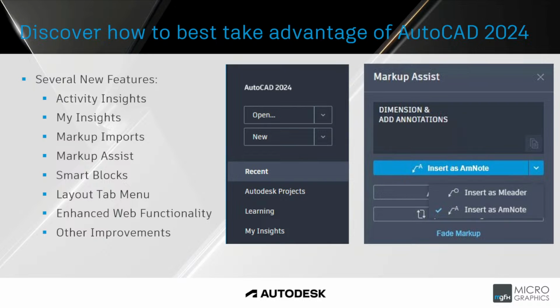Activity Insights helps bridge information gaps in your collaborative AutoCAD workflows. Activity Insights tracks events whenever a drawing file is opened and being worked on, similar to worksets within Autodesk Revit. It can also track some events outside AutoCAD, such as drawing renaming or copying in Windows Explorer.